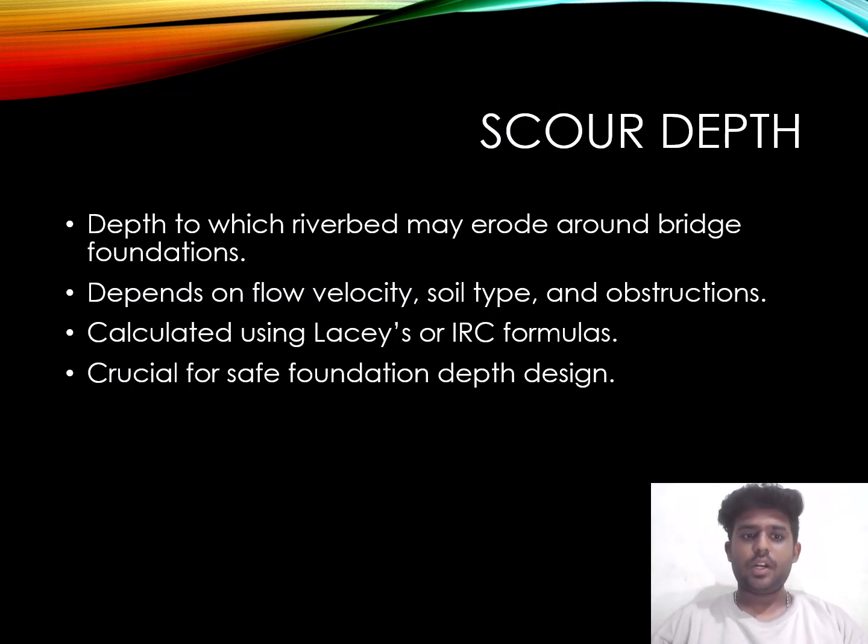Scour depth. Depth to which the riverbed may erode around a bridge foundation depends on flow velocity, soil type, and obstructions. Calculated using Lacey's or IRC formulas, crucial for safe foundation depth design.